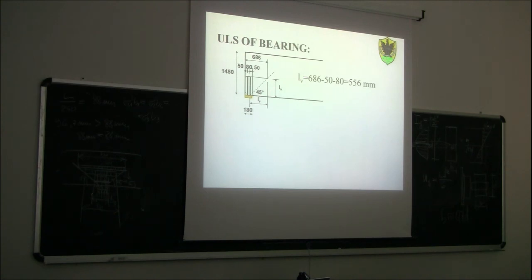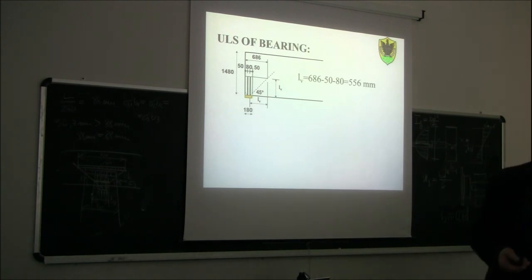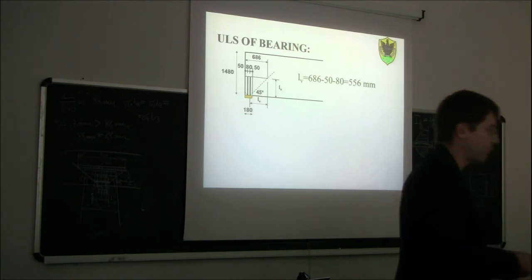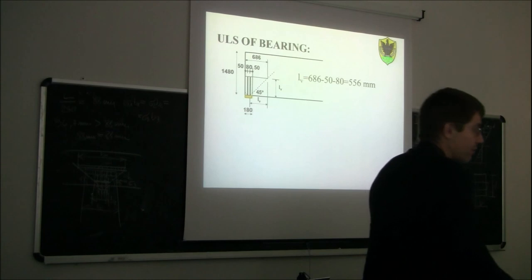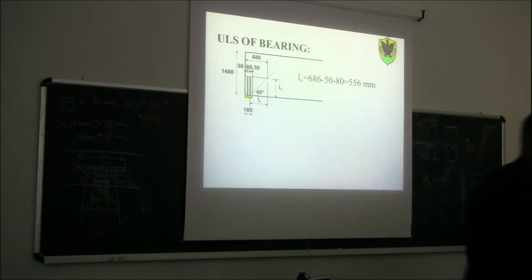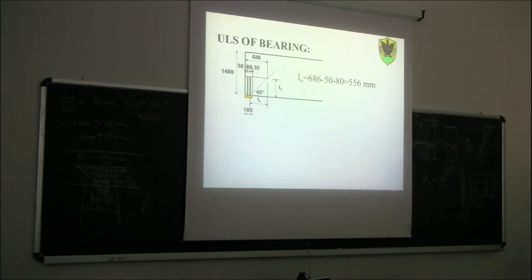It's like having a very slender pile in the soil. You have to transfer a certain value of load from the foundation to the soil. If you put one small pile that is too slender, it is going to buckle. It's going to break for flexural buckling. So the same thing may happen here. Okay? So we have to do a check of these screws for flexural buckling.